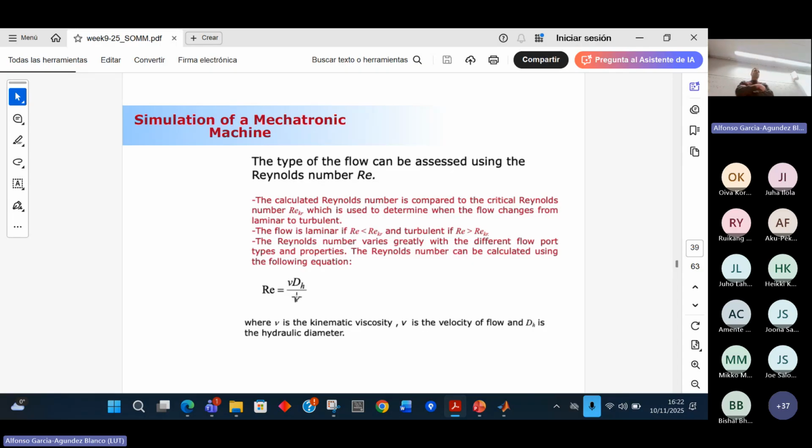Do you remember what the kinematic viscosity is from previous lectures? How can you compute the kinematic viscosity? I will try not only to provide new material, but also to review everything for the exam, okay? So do you remember how to compute the kinematic viscosity? If you remember, in the tutorial, we were introducing this numerical value too. So this kinematic viscosity is just the dynamic viscosity, that you usually denote by mu, divided by the density of the fluid, okay? It is just this kinematic viscosity.